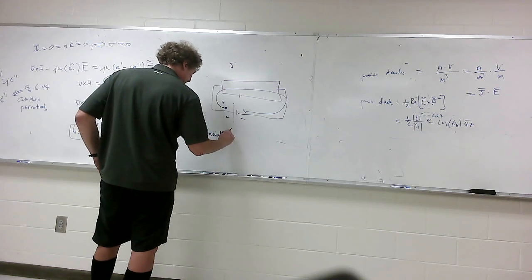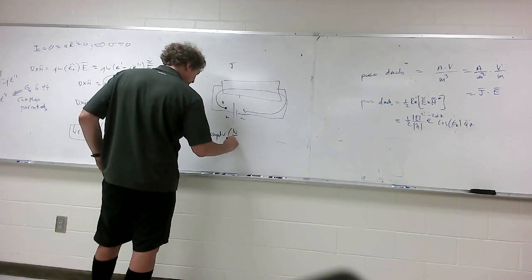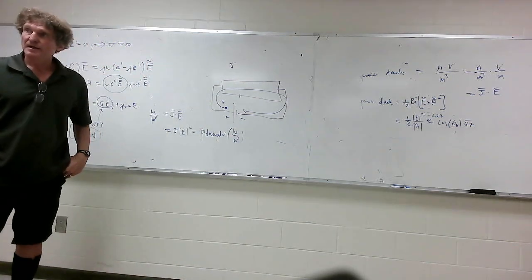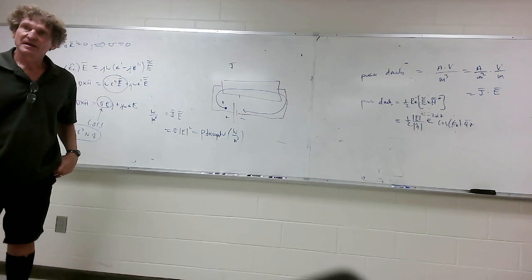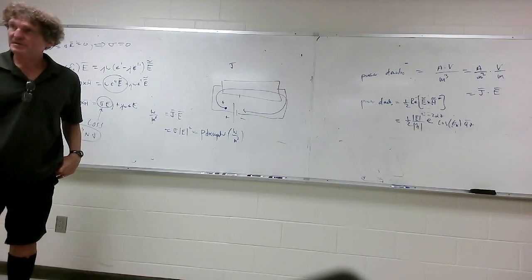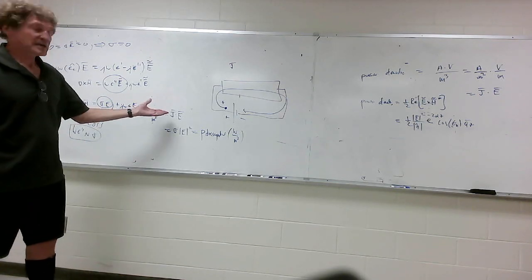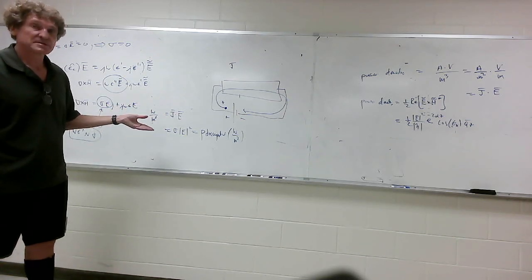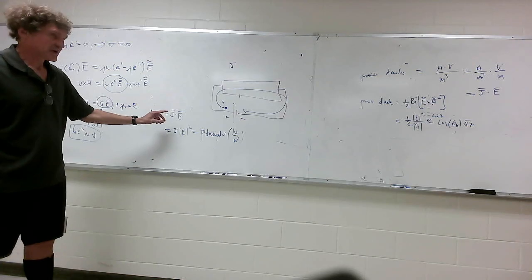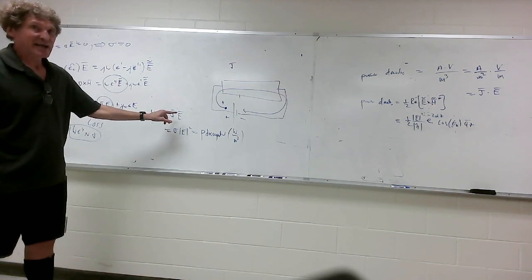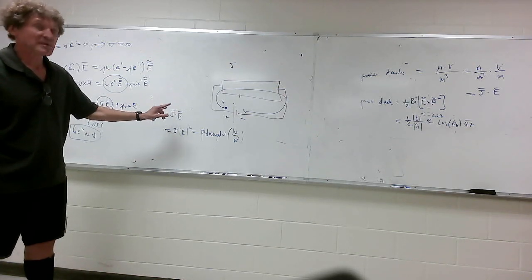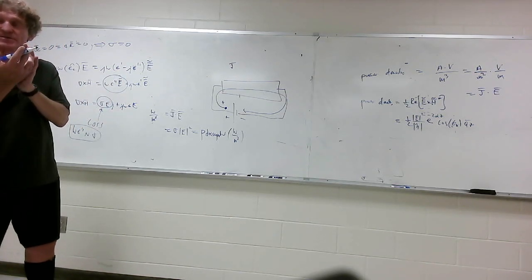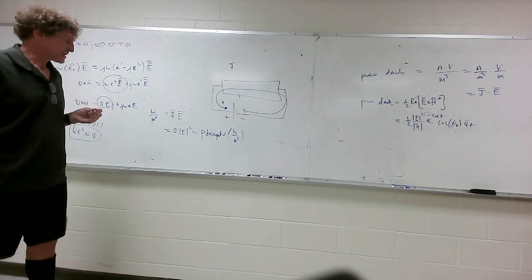And it would be a density, so it'd be watts per meter cubed. Do you all remember that? Do you remember this at all from MMAC 1 or not? You do? Sigma times E squared. The thing is, J is amps per meter squared, E is volts per meter. Amps times volts is watts. So this is going to be watts per meter cubed, dissipated. That's the amount of power or thermal heating, you might say, that's occurring in a volume of space.